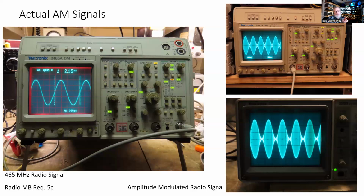Then at the receiver, the receiver takes the 1 megahertz or high frequency carrier, strips it away, and what we're left with is just a variation of the audio. That variation gets sent to an audio amplifier, and then we hear it as music or voice or whatever it is.